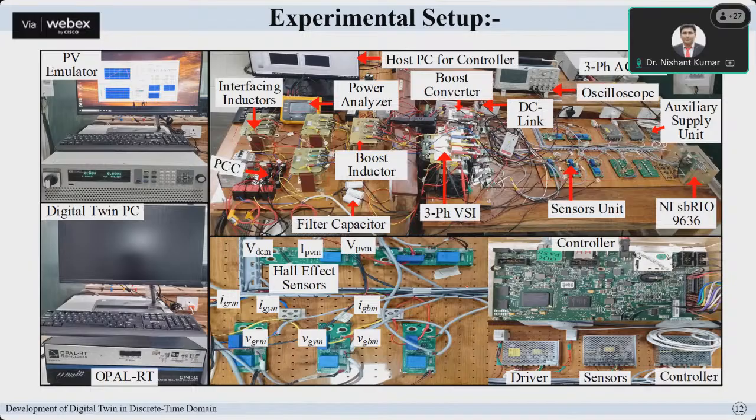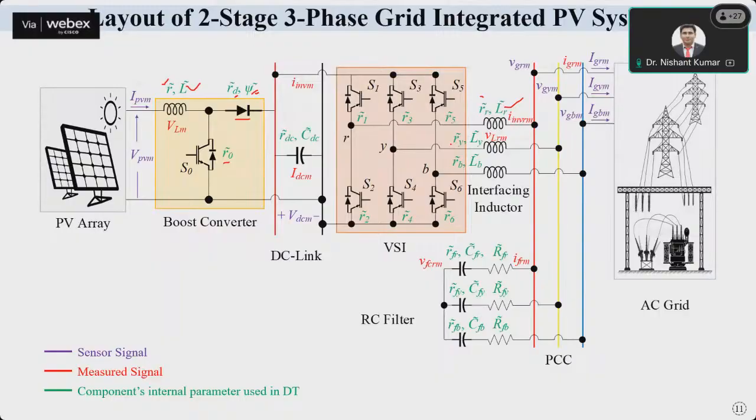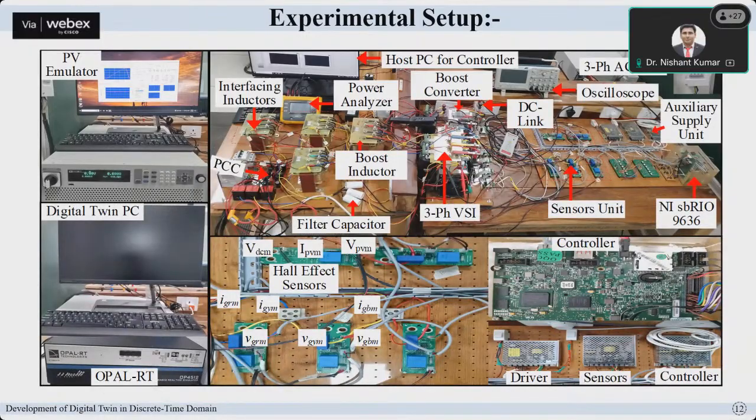You cannot do it through simulation only, because in simulations all these unknown parameters will be zero, since the components are standard ideal components, right? In ideal conditions all the internal resistances are zero. Wire impact will not be there. Temperature impact will not be there. So that's why don't go for simulation only. You should require one hardware setup.